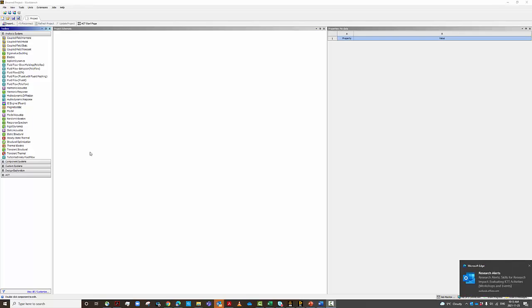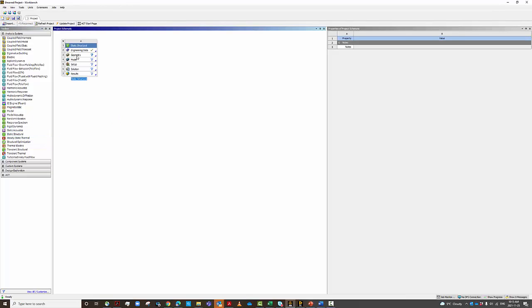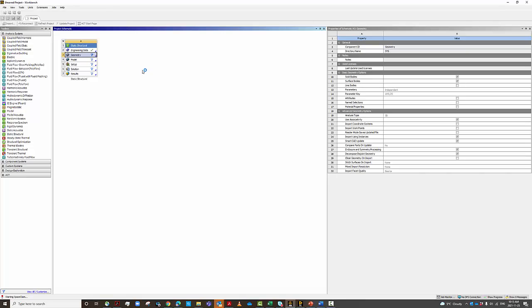If you see that you have reached a steady state, or that the change is not much, let's say, for example, 5%, then you know that your solution is no longer dependent on the mesh, or basically your mesh solution has converged. So I'll try to do a simple example for you and hopefully this would be helpful. So I'm going to go to static structural, and as you know, you can select the material. I'm just going to go directly to geometry, and I'm going to double click to start SpaceClaim.